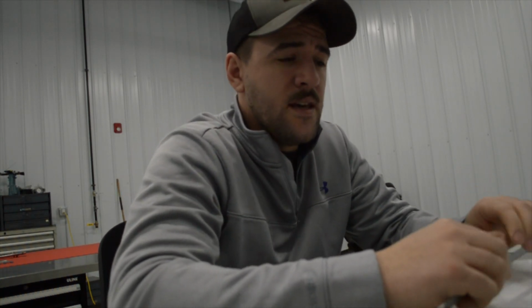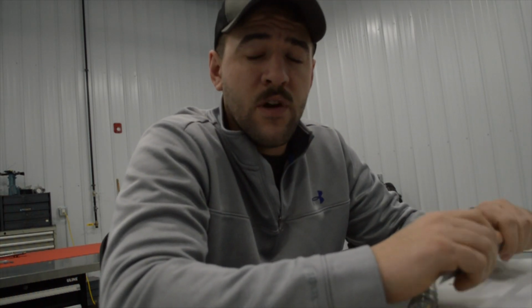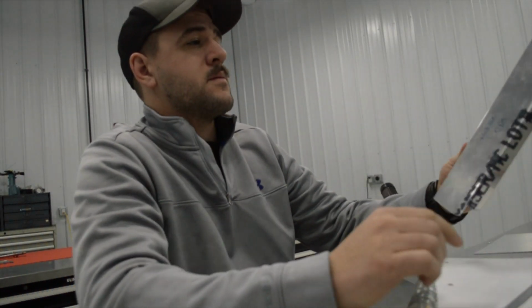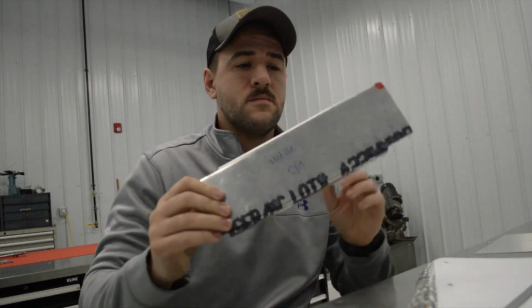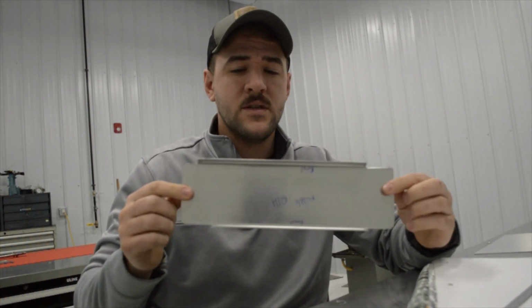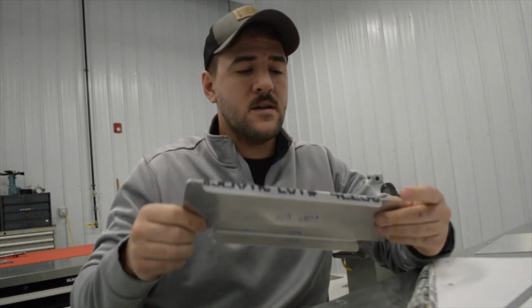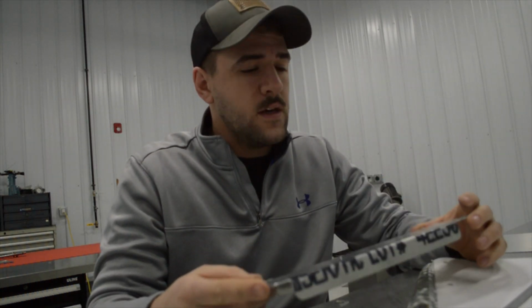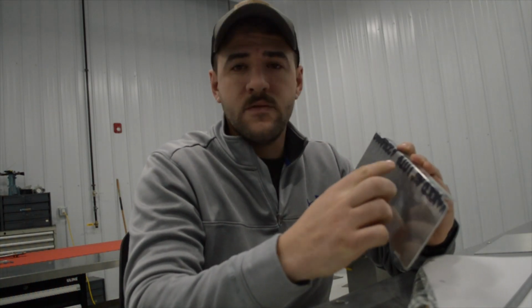It's not uncommon for us to get brand new planes in and have to modify them. Right now I am working on a King Air 360, and the owner wants a new type of cargo net in the back, and with that we need to build a few new brackets for the footman loops, which is just where the cargo net connects onto. So basically what we're going to be building is a bracket just very similar to this, a couple simple bends, and then a couple notches to be able to fit inside of the frames. And then we'll drill some holes to get the footman loops.